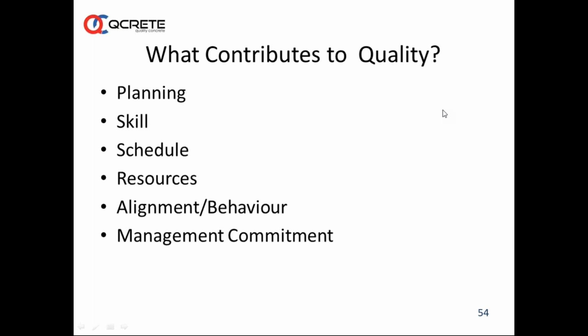Sir, can we use more quantity of GGBS than cement in preparation of concrete? Mr. Vishweshwaraya Solikeri. See, as per IS, it recommends 35 to 70% usage of GGBS in concrete actually. If we are using more than this, then it will not be regular structural concrete, and you are going away from the IS code, and you can use it with certain alkali activators or some other things.